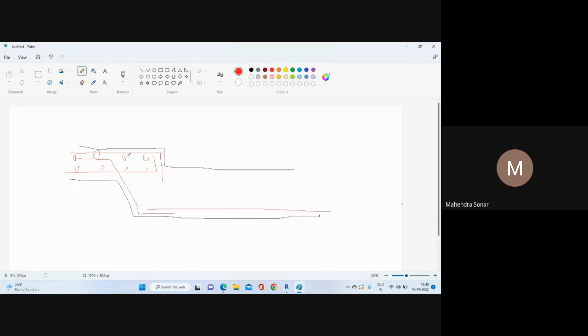Then after that you need to add one more Z bar here, and this is your top reinforcement like that. So you can stop here. This is your top reinforcement, and this is your other direction reinforcement, the transverse direction. So you need to model this part also. We have modeled up to here. If this gap is 1 meter, you need to add this.